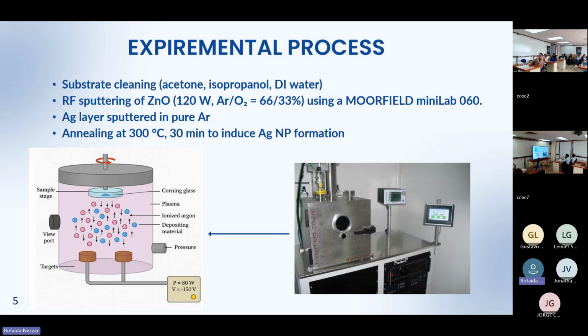And the silver interlayer was deposited in pure argon, and then after deposition, the film was annealed at 300 degrees for 30 minutes to encourage silver to agglomerate into nanoparticles inside the zinc oxide matrix, which we expected to enhance both the plasmonic and electrical behavior.